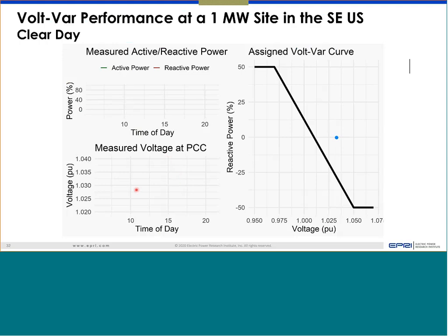A couple of times you'll see a step change. Those are the regulator or cap bank switching. And here, this is the configured Volt-Var curve. If you notice, there is no dead band. We actually configured that in the field for a megawatt scale plant. In this particular case, the reference point was around 1.02, something like that, maybe 1.1, the operating reference point.